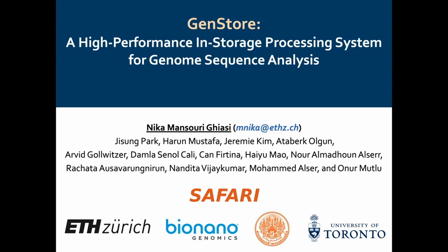So for the software implementation and the HDL implementation, we have already open-sourced them in the SAFARI GitHub repo. But how would one practically use it? For software, it is explained in the repo how to use it, but for hardware, there are two ways I can see. There are some systems that already try to integrate FPGAs densely within the SSD controller that would enable near-storage processing. So it is possible to implement the HDL code inside the SSD and also handle the control flow from whatever that FPGA is using to interface with the NAND flash chips. So that is one way.